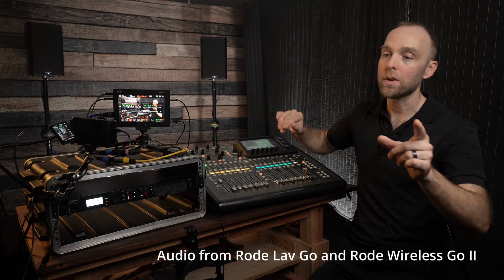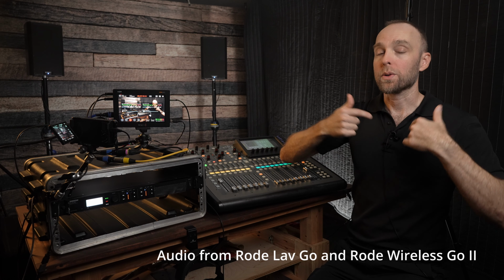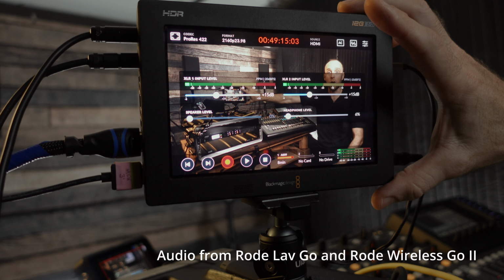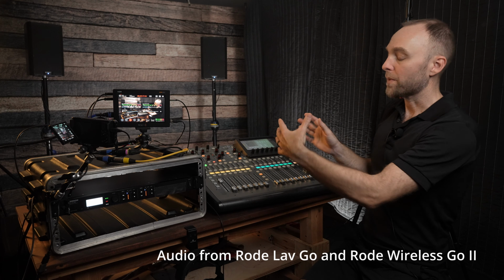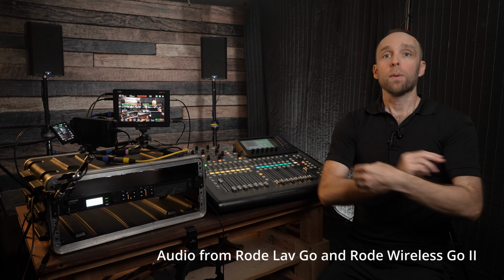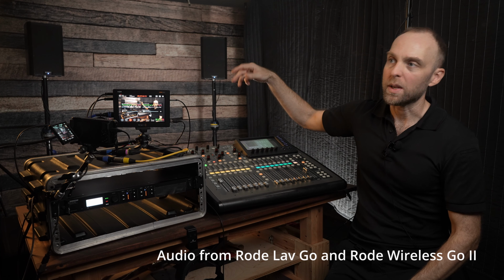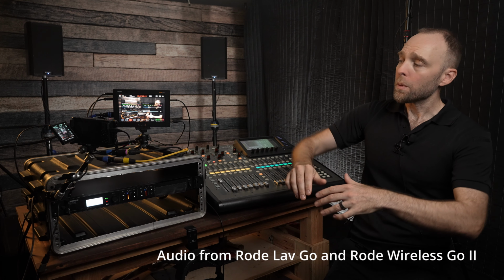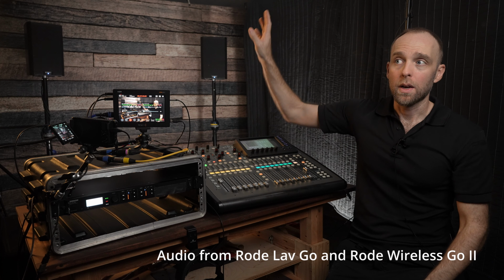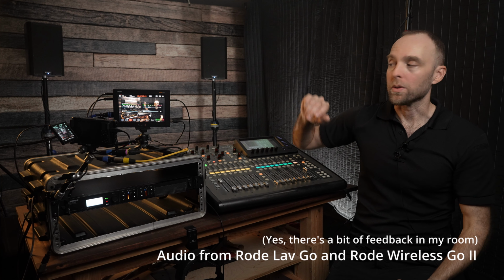And you're actually still hearing me on the Rode Lav. So to let you hear the audio that's getting recorded through this system over to the Blackmagic Video Assist, we have to go here and set our audio level here. If this is how the front of house engineer, the A1, is gain structuring their system, they're like, cool, my job's done. I've got audio out of my system. I'm good to go. I can hear the speakers hissing a little bit, but who cares? It's in the room. But the recording operator, or anywhere we send this signal, is getting a noisy signal. Some of that noise I'm hearing from the speakers is from the console, some of it's from the speaker itself.